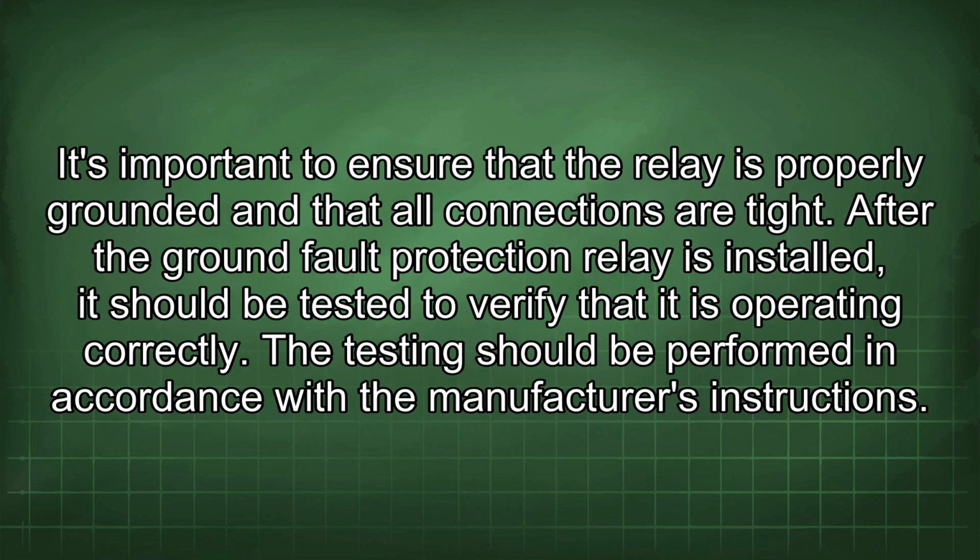It's important to ensure that the relay is properly grounded and that all connections are tight. After the ground fault protection relay is installed, it should be tested to verify that it is operating correctly. The testing should be performed in accordance with the manufacturer's instructions.